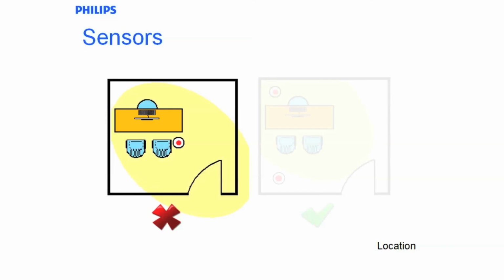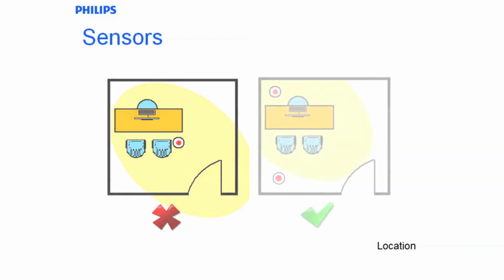So what will happen when this person walks into this room? They will be walking into the room parallel to the beams coming out from the sensor. So the likelihood of crossing over the beams means they won't be picked up that well. What will get picked up fantastically is anyone walking past that office. They will be crossing the beams over, so you will get a lot of false triggers from corridor traffic. More importantly, when someone is sitting at the desk, they will be sitting with not much movement, and the likelihood of the sensor turning off is pretty high.